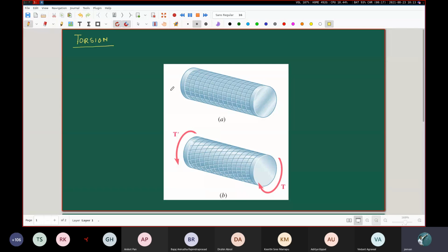And when those questions crop up, the two things to be kept in mind are the geometry, certainly, because it's always a trade-off which the engineer has to think about. On the one hand, the lower the amount of material used, the lower the cost, so it is better to have slender members using less material. But at the same time, if you make it too thin, perhaps it will not be able to sustain the deformations and the twisting action. So there is always a compromise and a trade-off.